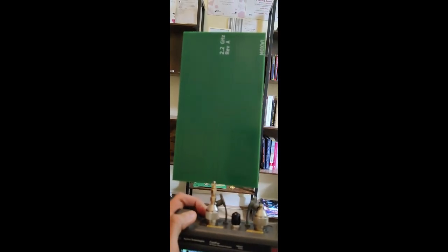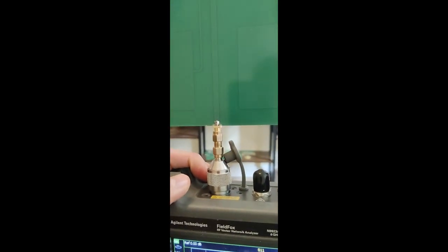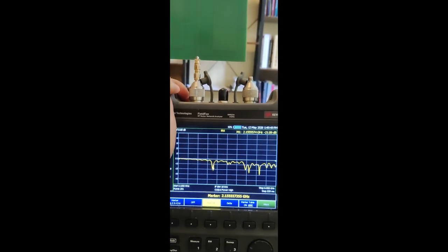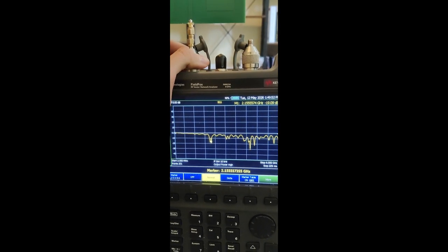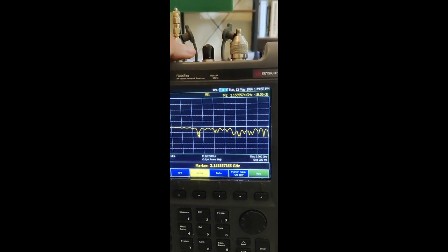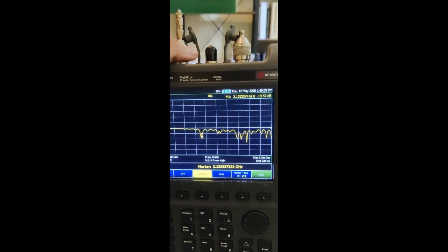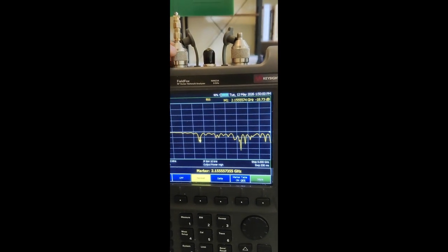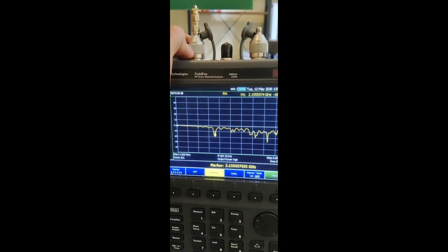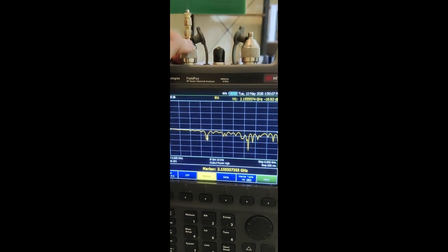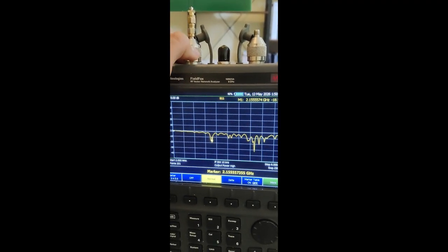The antenna was then manufactured and fabricated. An SMA edge connector was attached to the edge of the microstrip trace, and the signal trace was soldered directly onto the PCB, and then the ground pins were soldered onto the bottom of the antenna. From the measured signal, it seems the S11 is resonant and matching at 2.155, which is not the frequency that was designed for, which was 2.215. This would likely indicate a difference in the dielectric constant, probably higher than the one used in simulation.